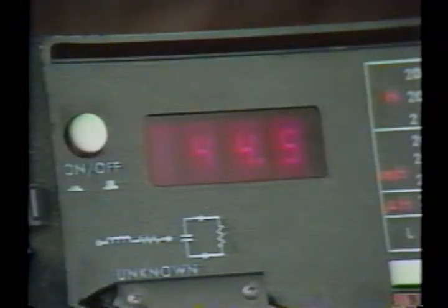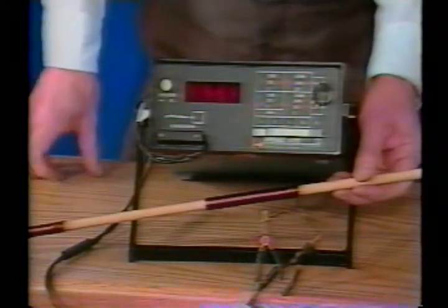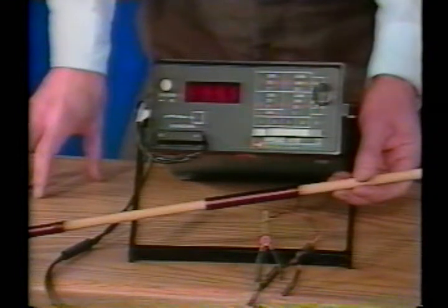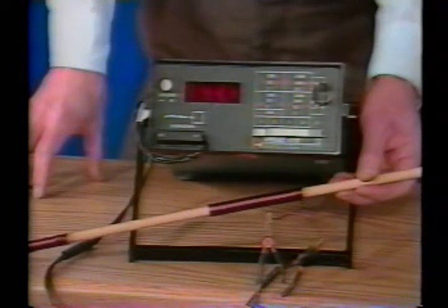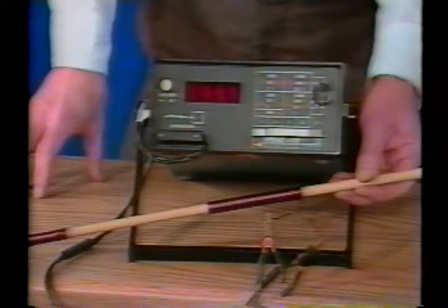The surface for a many-turn coil used in Faraday's law is geometrically complex, as the bounding contour to the surface follows the path of the wire. For a tightly wound coil, the magnetic flux linking this surface is the sum of fluxes linking each turn. Since the magnetic flux per turn is proportional to the number of turns, if each turn links the same flux, the total flux linked by the coil is n times the flux per turn. The coil self-inductance is then proportional to the square of the number of turns.